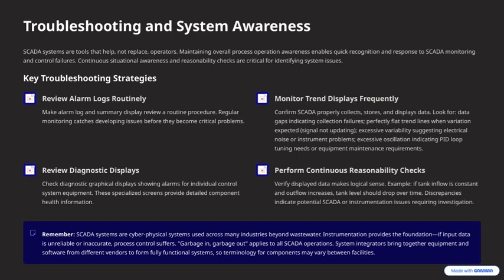Remember, SCADA systems are cyberphysical systems used across many industries beyond wastewater treatment. They rely heavily on instrumentation, which forms the foundation of the system. If the input data is unreliable or inaccurate, the entire process control can suffer. That saying, "garbage in, garbage out," really applies here.